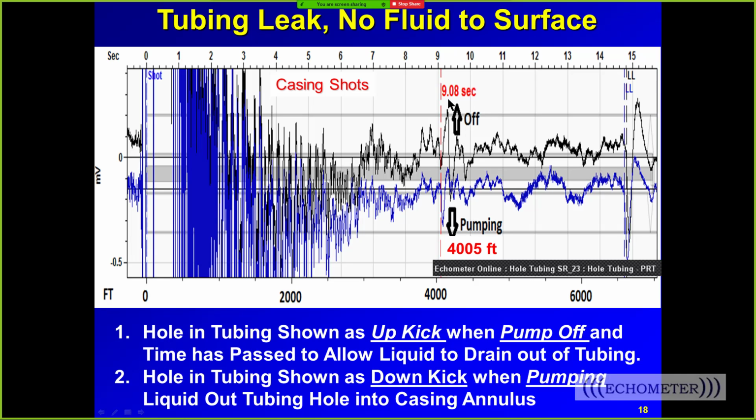And so this was a way for us to confirm about 20 years ago. And then sometime between 20 years ago and the present, we realized that, hey, we can shoot down the tubing and see the rod couplings and actually use the technique to shoot down the tubing to troubleshoot rod pumped wells with an acoustic instrument. And that was, I don't know, maybe 15 years ago. Someone sent me some data on a well that he'd shot down the tubing and could see the rod boxes.